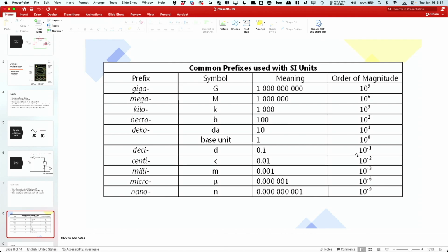For our purposes, at least with the electronics, we'll basically be completely under the unit line. I can't think of any reason that we would need to use any of the larger ones. Like kilo ohms, mega ohms. Resistances are going to be in ohms, and the smallest ones that we'll use are like 220, 330 ohms, but we'll also use 1K, 10K, 4.7K, things in that kind of range.